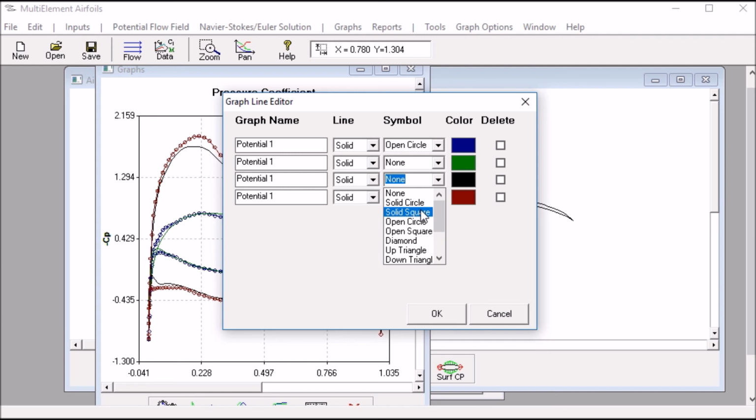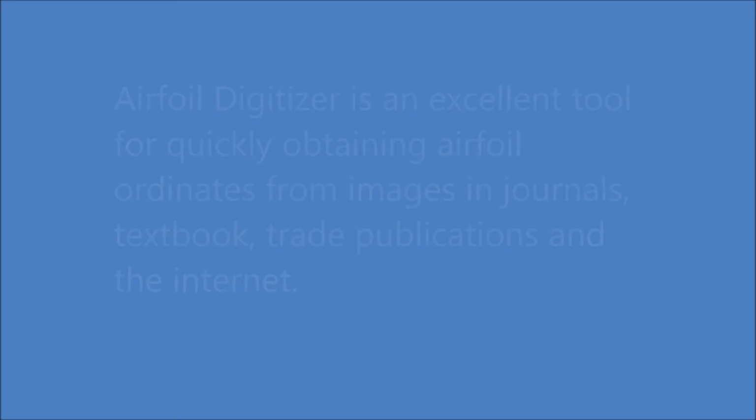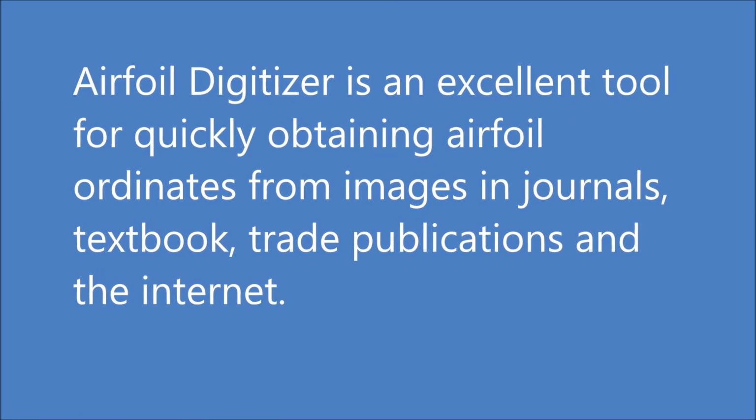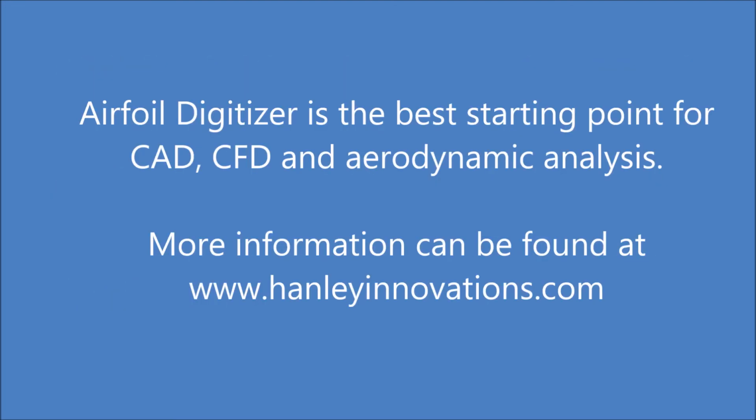Looking at the two sets of data, we see that the pressure coefficients from both the UIUC database and the NACA airfoil generator are in good agreement with the Airfoil Digitizer data files. Airfoil Digitizer is an excellent tool for obtaining hard-to-find airfoil ordinates from images.